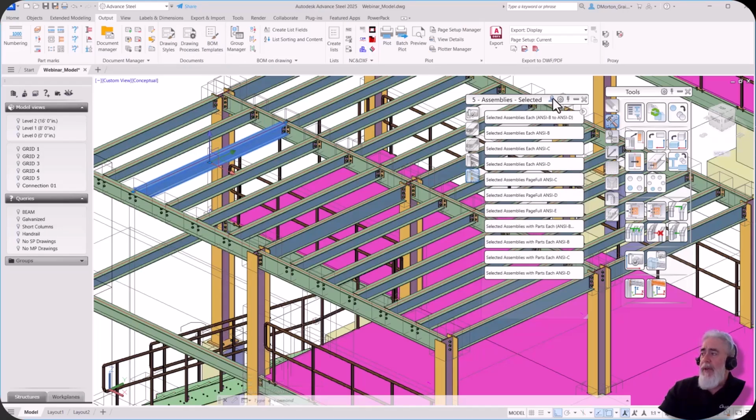But I want to make sure that I'm under my user settings, because the little flag that you see up here at the top of your drawing process dialog or your palette is the out-of-the-box styles, the ones that are locked, the ones that can't be changed. So you have to click on that to change to this little blue guy, which is your user styles. This is the one we just modified. So now I'm going to go to my user style. I'm going to say make a drawing of that beam using, and selected camera, page full, and 2D.